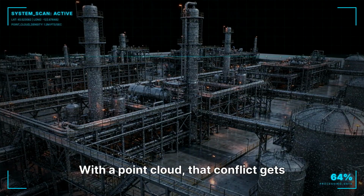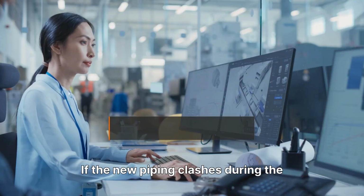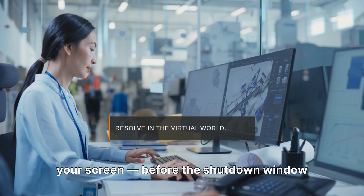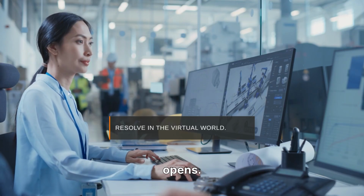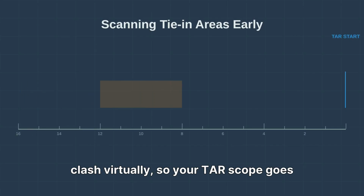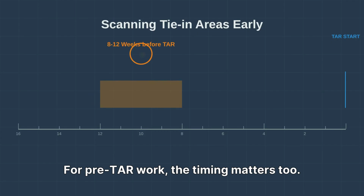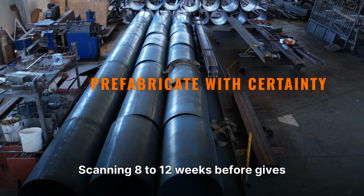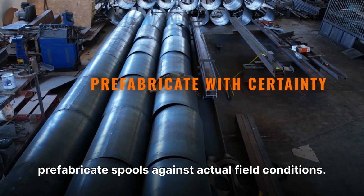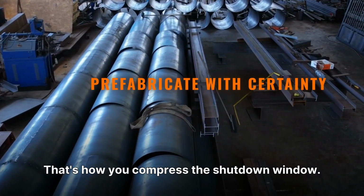With a point cloud, that conflict gets caught in the model, not in the field. If the new piping clashes during the 3D design review, you find it on your screen before the shutdown window opens. The goal is to close out every clash virtually, so your TAR scope goes in clean. For pre-TAR work, the timing matters too. Scanning 8 to 12 weeks before gives your piping team enough lead time to prefabricate spools against actual field conditions. That's how you compress the shutdown window.